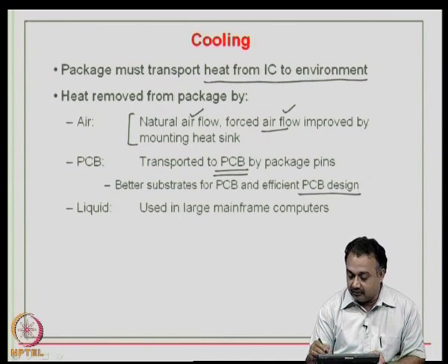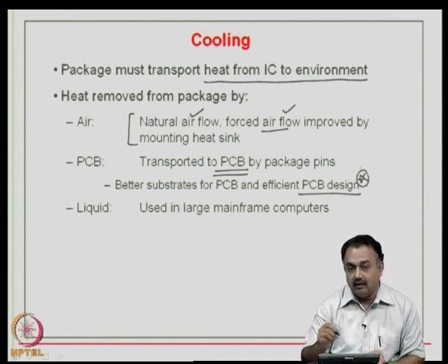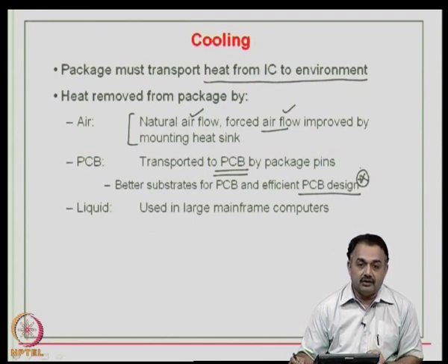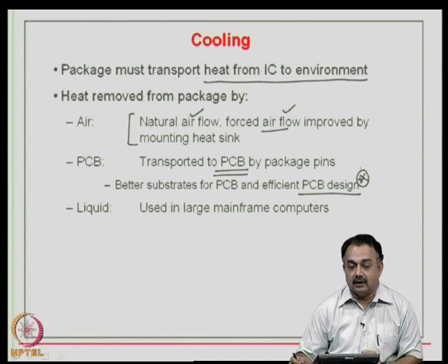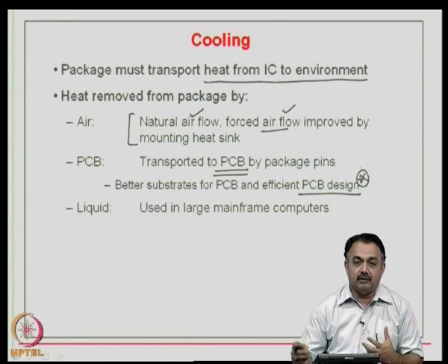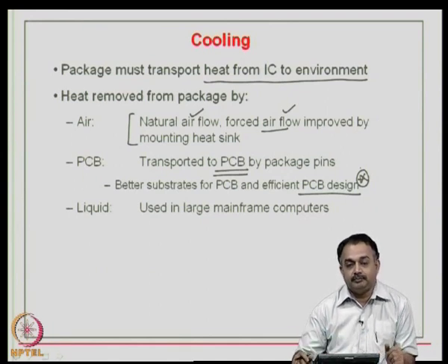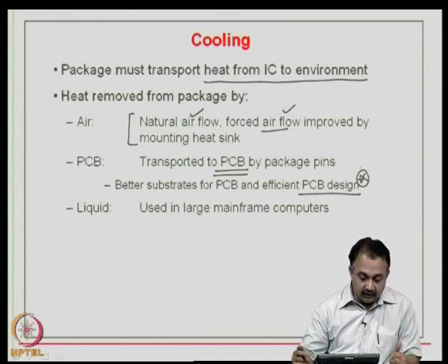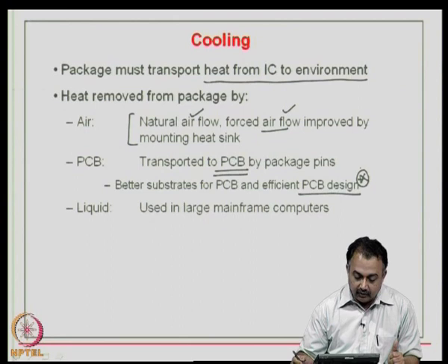Therefore, PCB design today does involve a lot of thinking by the designer, engineer, to place your components in such a way that your PCB is not affected and the PCB effectively acts as a good heat sink. There are other methods of designing a PCB where from the package pins you can remove heat through copper layers that can act as a heat sink embedded in one of the layers of the printed wiring board. You could also use liquid.